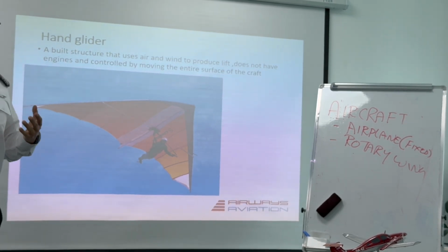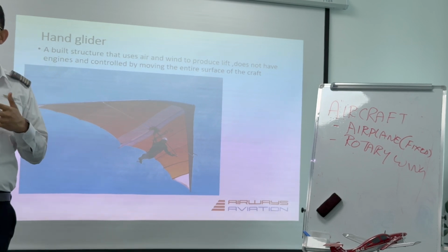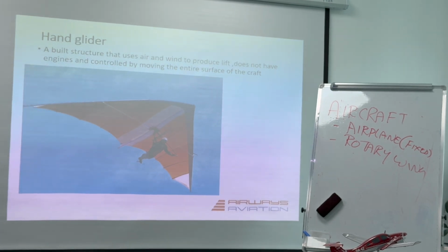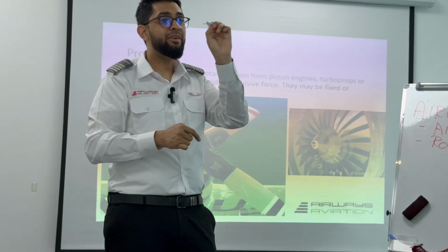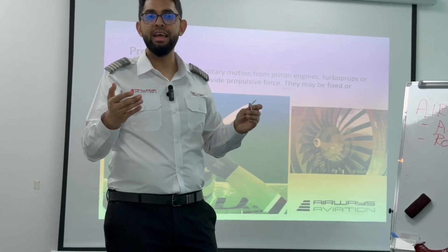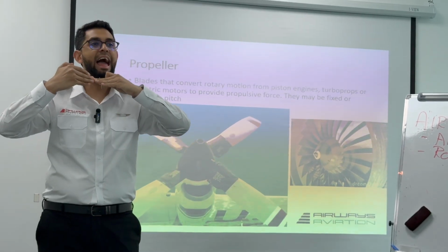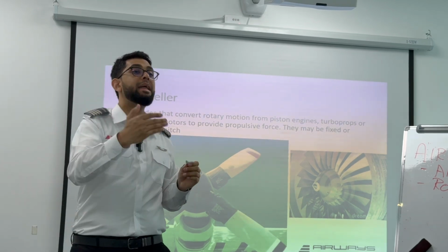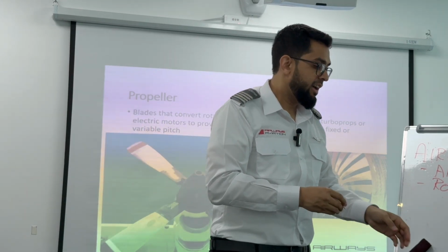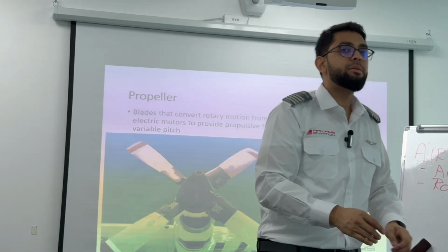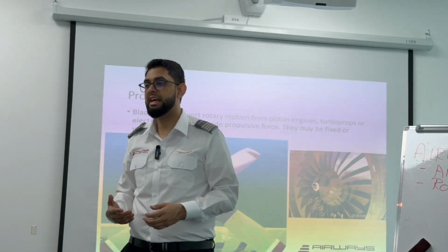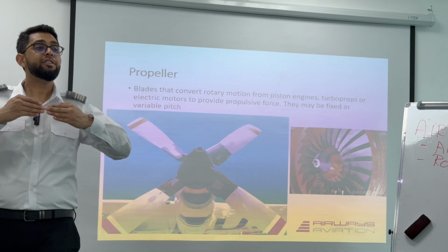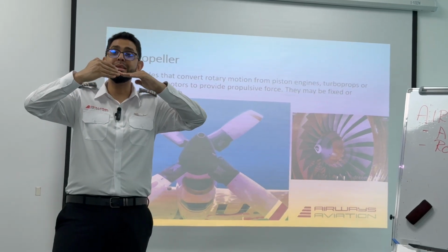A hot air balloon is also under the aircraft category. Blimps and airships are also categories of aircraft, right? So, when the propellers are simple, they are fixed at a certain angle. These propellers are fixed. But what if I want to get better performance out of your engines? Some of the high performance aircraft, some of the advanced aircraft, or some of the multi-engine aircraft have the option for you to change the blade angle